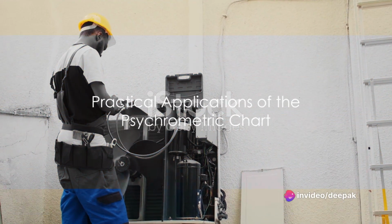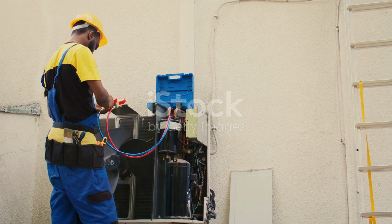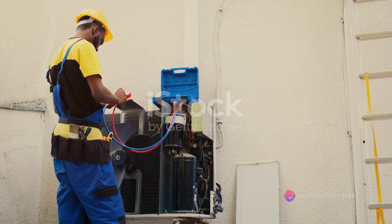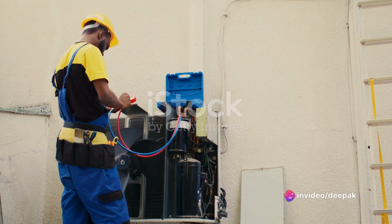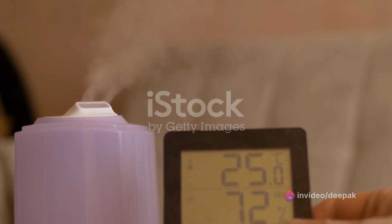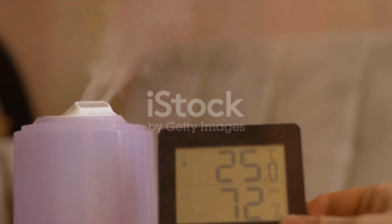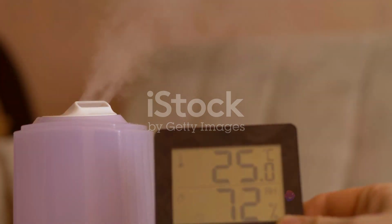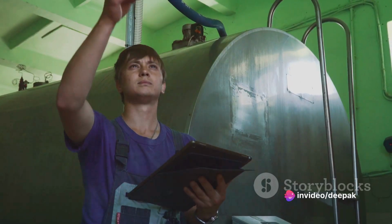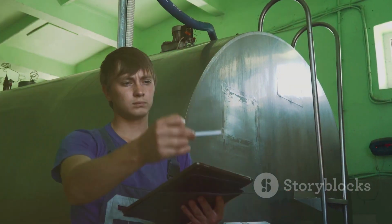Now, how does one use this chart? Engineers and scientists use the psychrometric chart to analyze air conditioning systems, to predict how changes in temperature, pressure, and humidity affect human comfort, and even to forecast weather. To use the chart, you start with two known properties of the air, such as the dry bulb temperature and relative humidity. Find these values on the respective axes, and where they intersect on the chart, that's your air's condition. From that point, you can read other properties like dew point temperature or specific volume.